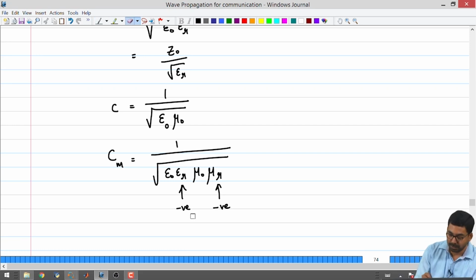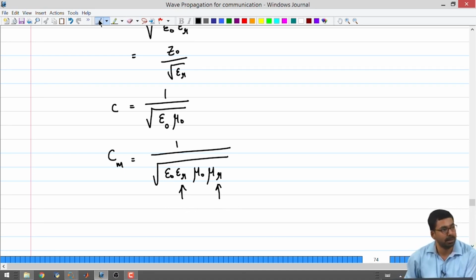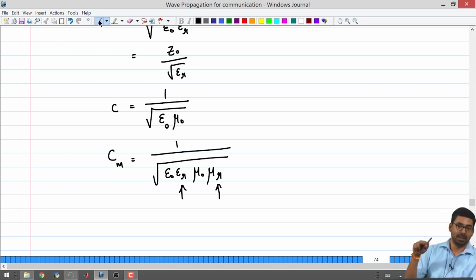But for the sake of preventing confusion, I will just remove all these things, so that you do not make these things in the course. We will not be seeing all these advanced cases in the course. So I will stop here. These are some things that I wanted to say, because in the transmission line we did not have the time to talk about negative capacitance, negative inductance and all that. We did see negative resistance and conductance being equivalent to making gain. We did not talk about the rest, so I thought I will just mention this at this time.